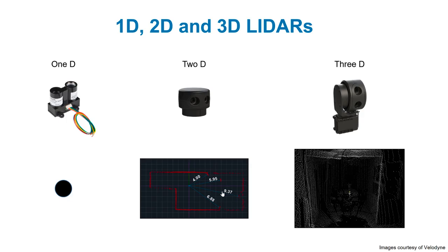So far, you have seen static 1D and rotating 2D LiDAR sensor concepts, corresponding to the left and middle sensors here. By adding a third degree of rotation, a 3D mapping of the world is possible. The vertical rotation can be 360 degrees, but here it typically makes more sense to sweep back and forth, optimizing useful measurements over, for example, 30 degrees vertically. Instead of having a sweep vertically, static laser beams are sometimes used at fixed angles, but it's then difficult to get the tens or hundreds of measurements over the vertical angle that is to be covered.